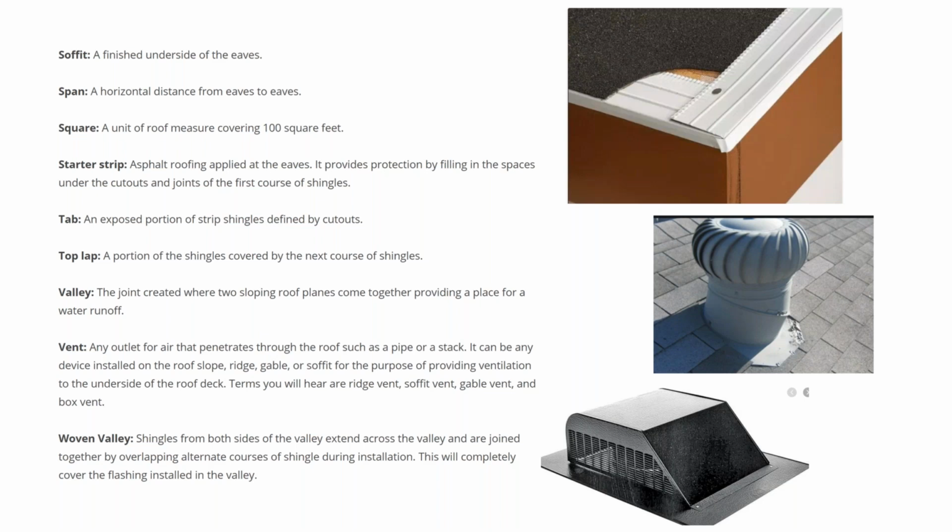We talked about valleys. This is your drip edge. You'll see this is missing sometimes on houses. I'm not sure why somebody would not put a drip edge, but it goes underneath the shingle. And again, it's to prohibit the water from getting underneath and rotting out that sheeting.